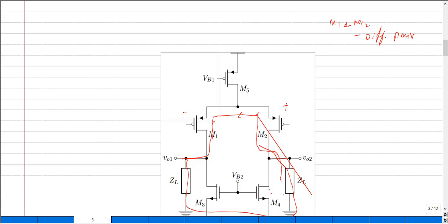Since only two transistors participate in this small signal operation, this circuit is used in high frequency or high speed differential amplifiers. Also, the circuit we have drawn is a pretty simple configuration. There is not much difficulty in doing this because we want an identical system across both these branches. So even from the design perspective, the circuit is very simple.